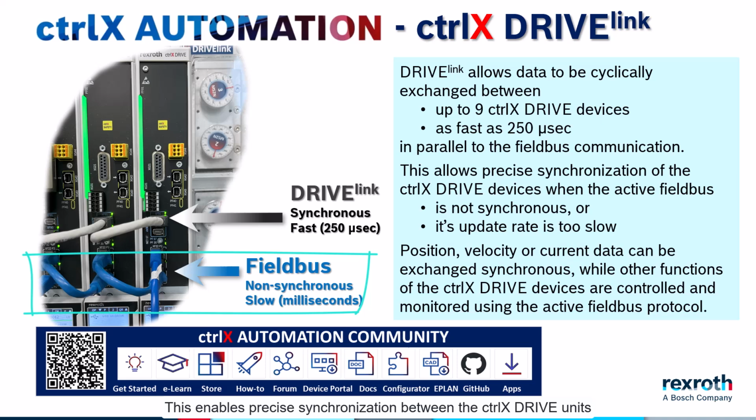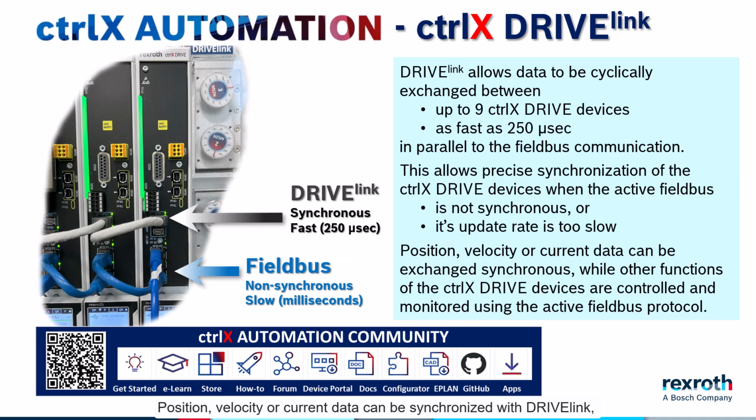This enables precise synchronization between the ctrlX drive units, when the active fieldbus is not synchronous or the update rate is too slow. Position, velocity, or current data can be synchronized with DRIVElink, while the overall ctrlX drive functions are controlled and monitored using the active fieldbus protocol.